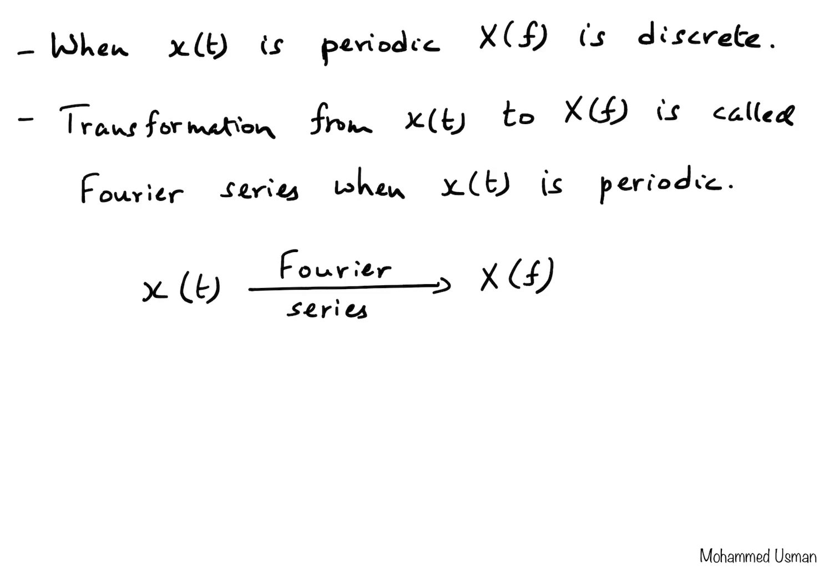It is basically going to give us the frequency content present in the signal. We want to find out the different frequency components that are present in the signal, and identify the magnitude of each of those frequency components as well. Or in other words, we want to break the signal down into its individual frequency components, so that when we add those frequency components in the right proportion, we get back our original signal. That's the whole idea behind it.